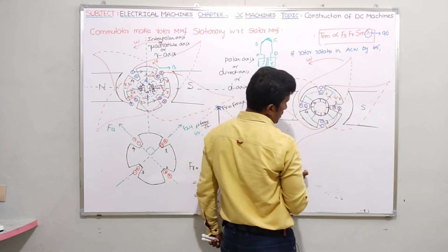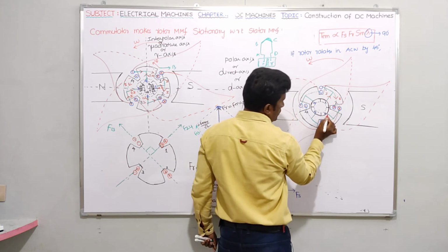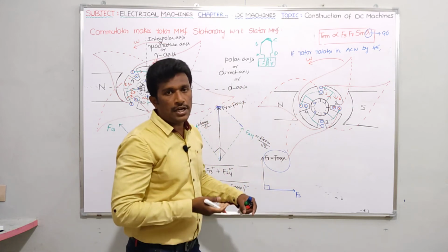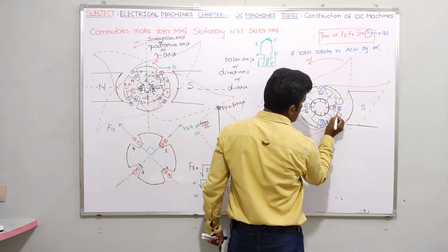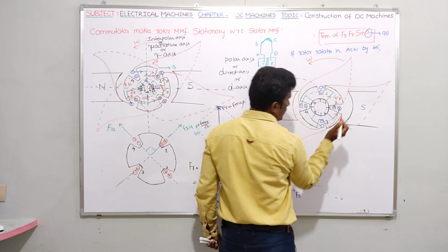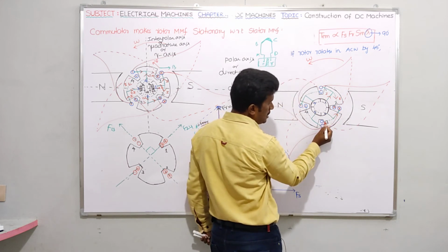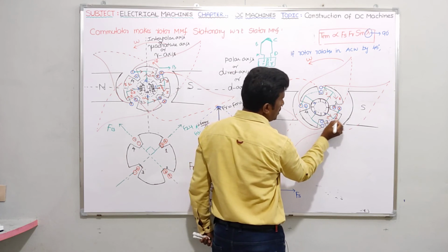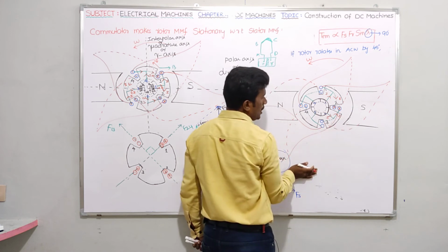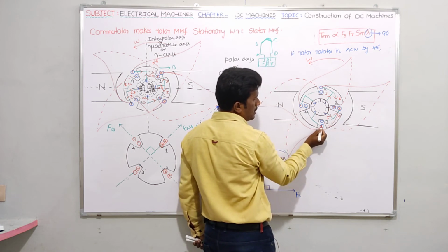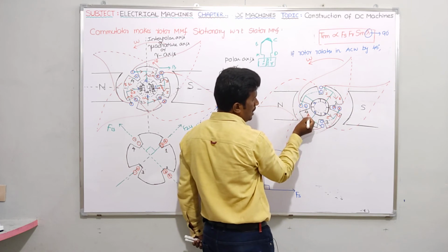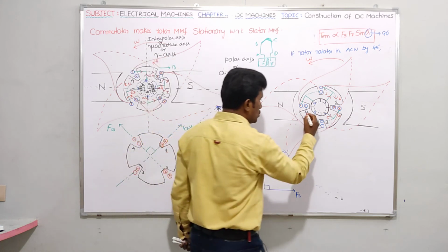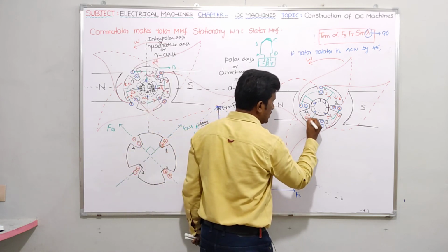Okay, now guys, what about this one? If it is segment number 2, guys, here getting cross. Cross means direction of current entering into the board. Into the board means arrow mark should be like this. Do you have any current in this slot number 3? No. Therefore, obviously this current will be coming from the segment number 2 only, I amperes. Once again, I amperes here. Now, do you have any current from this slot number 3? No. And do you have any current from this slot number 4? I can say yes. Dot. Dot means coming from the board. Therefore, arrow mark should be like this. I value should be like this.